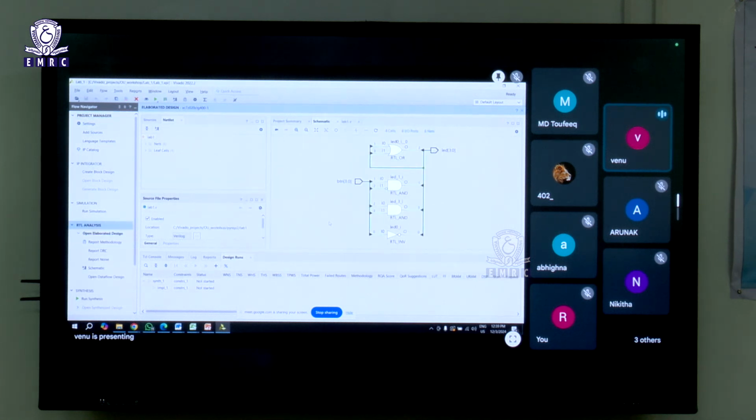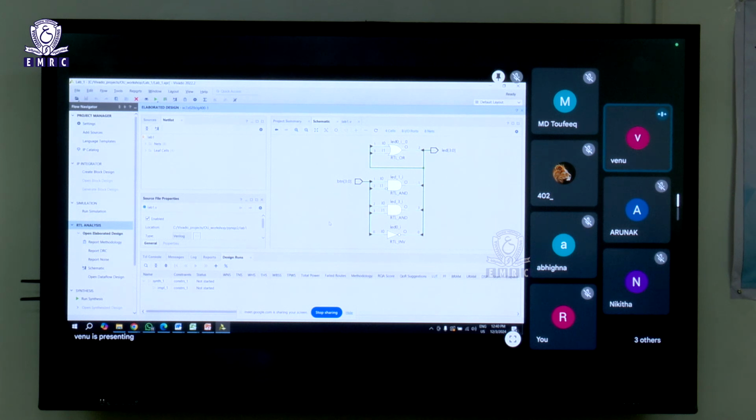Okay. So the next thing, sorry. Now what we'll do is we'll try to simulate our design. So we all already know that we can force our input. In the design, we can force constants, force our inputs and understand what is our output. But it is very cumbersome when it comes to high-end designs with a lot of input. So that is where a test bench file comes in. A test bench file is a set of scenarios that you want to test. Test cases, you can say. Okay. A bunch of test cases will be added onto a file to run over our design.